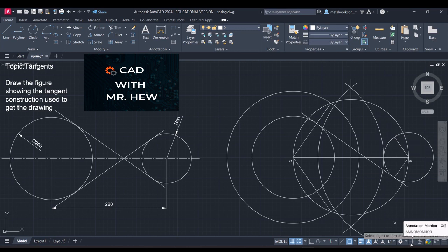We're going to clean up the drawing, all right? Good. Now the next thing we're gonna do, we're gonna draw the internal tangent for the one that's going below here. All right. So where the normal intersects the original circle, we're gonna draw a line from that point going up to this point, which is the point of tangency. Enter. All right. So good job if you're following so far.